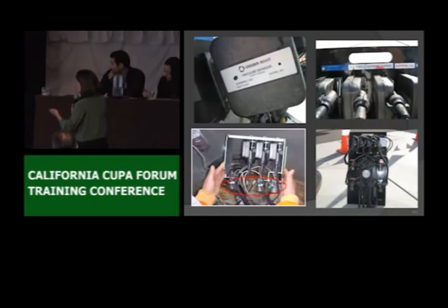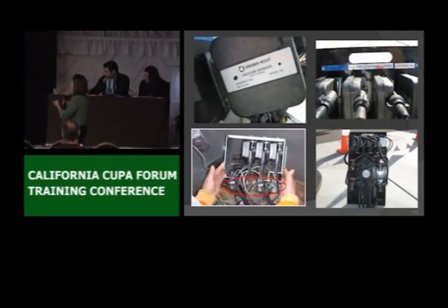And here's some examples of what the vacuum sensors look at. Here's obviously a Veeder-Root brand. So you're going to have one sensor per zone. And like I said, each zone has 1, 2, or 3 or so components. And the programming, your Veeder-Root printout should be able to tell you what components are monitored under each vacuum sensor.